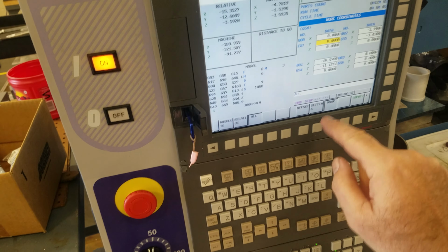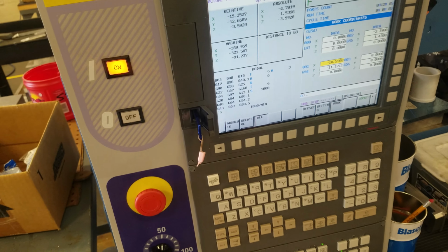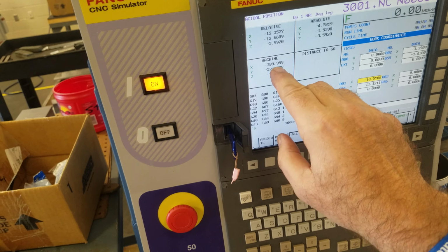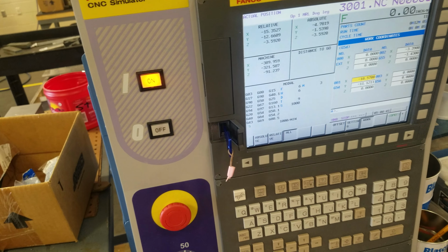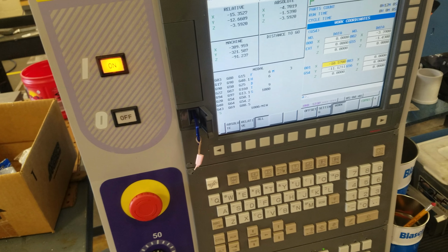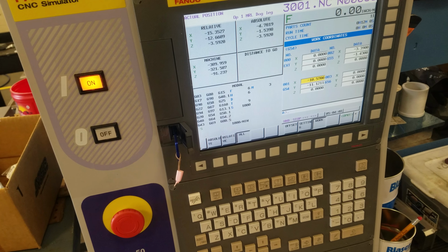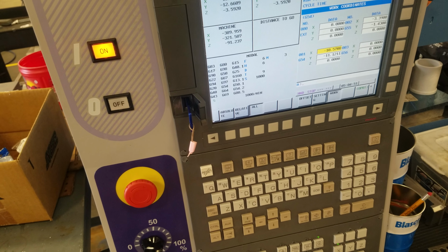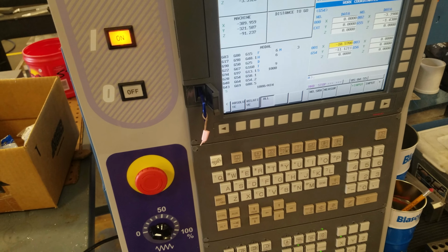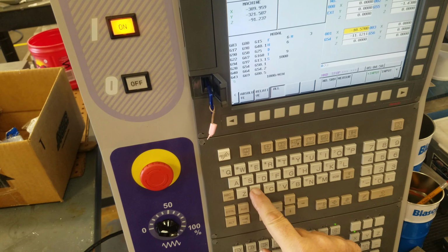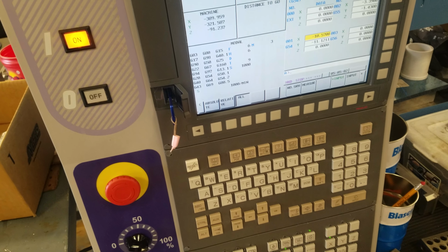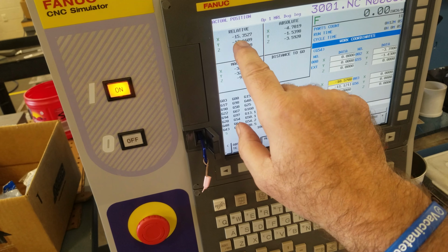What I want to do is update my G54, which is right here. So there's my relative number. You can convert this from metric, but it'll end up being that number right there. Make sure these are 0 when you start off. Alright, so now we've got to set this coordinate. I'm going to go to the operator screen, and I'm going to type in X measure. Format error. I saw somebody else do that. So I really need that number right there.